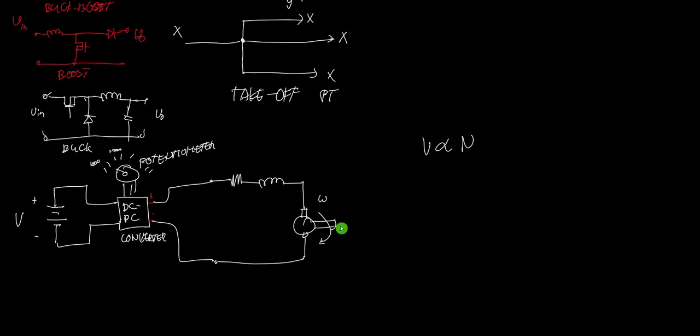But if you are the operator, you can check it by using a tachometer. You measure the speed here. If it's really 1000 RPM, then you stop the rotation. It's really accurate 1000 RPM. But in reality, we don't do that. If the motor is inside something, you cannot access the motor, and it's a problem.